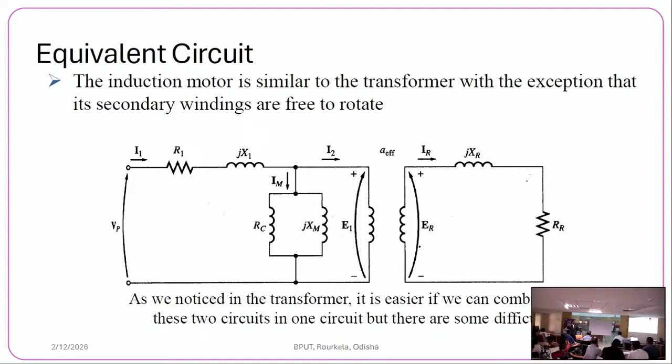So we don't have stator, primary and secondary is what we use for the transformer. In the primary winding, we use supply, due to that alternating voltage, one flux is produced in the core, which is alternating. On the same core the secondary winding is there, so the secondary winding is linking with that alternating flux. So EMF is induced in the secondary winding, that is due to N d phi by dt. The secondary also gets alternating EMF. Therefore, frequency is constant.